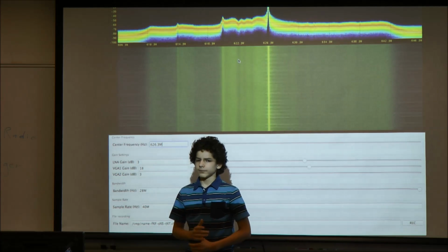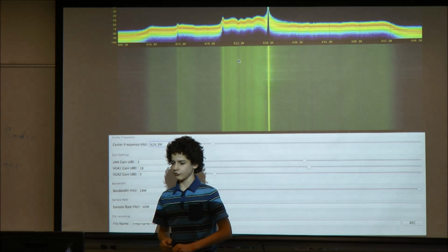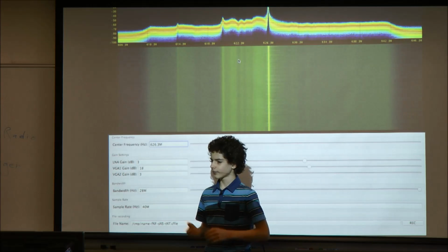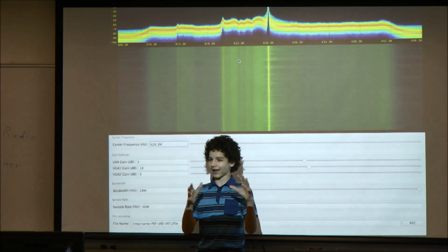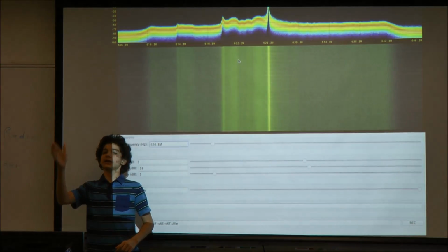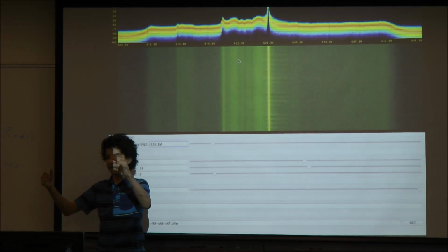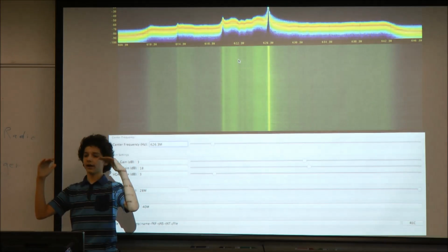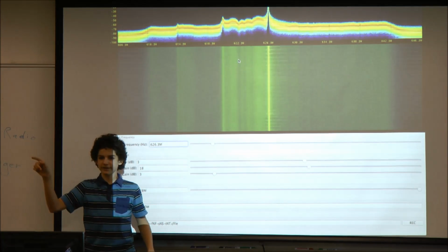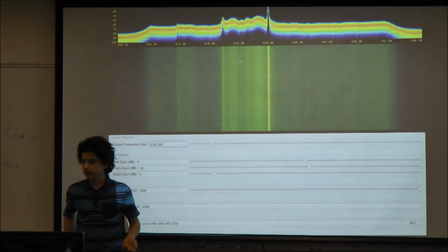I know someone, I believe, wrote a program for it. I'm not sure if it's available. It wouldn't be too hard. You'd probably just use GNU Radio, and you'd have to write something yourself or mash other stuff together. But essentially you'd say, go through the frequency, look at this bandwidth for say 10 seconds, compute the FFTs. If the signal is above say negative 50 decibels, print out that frequency, and then you could go look back at it later. It's like study at home.